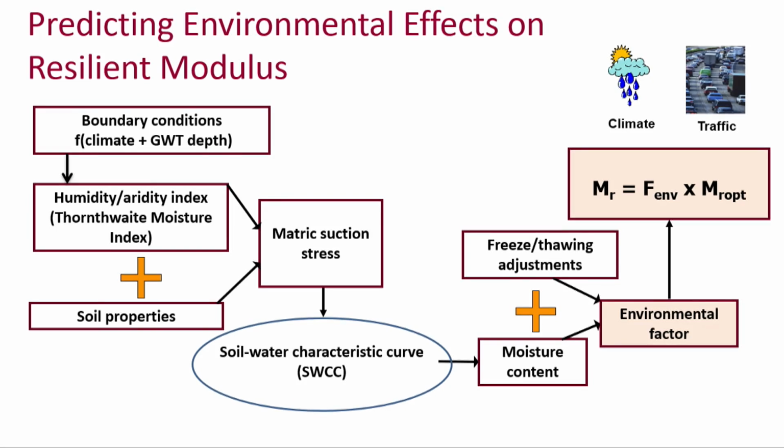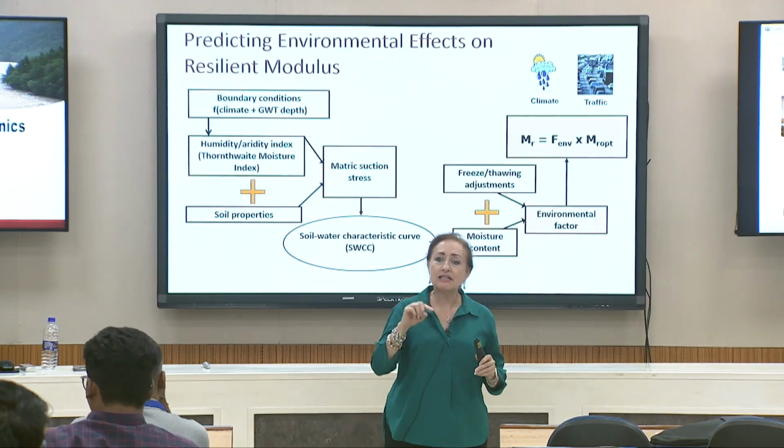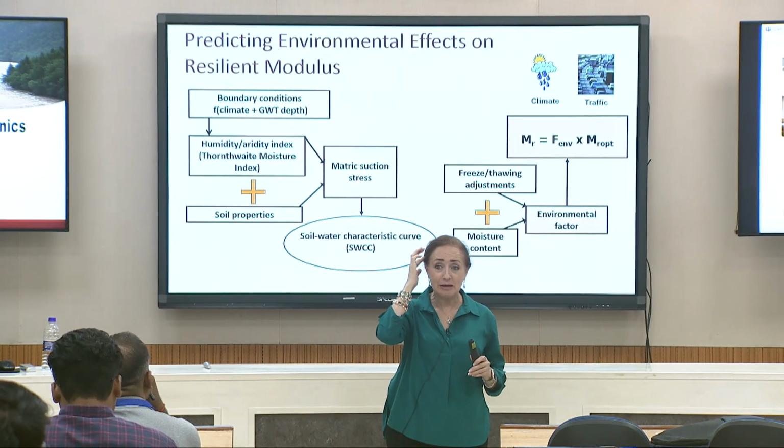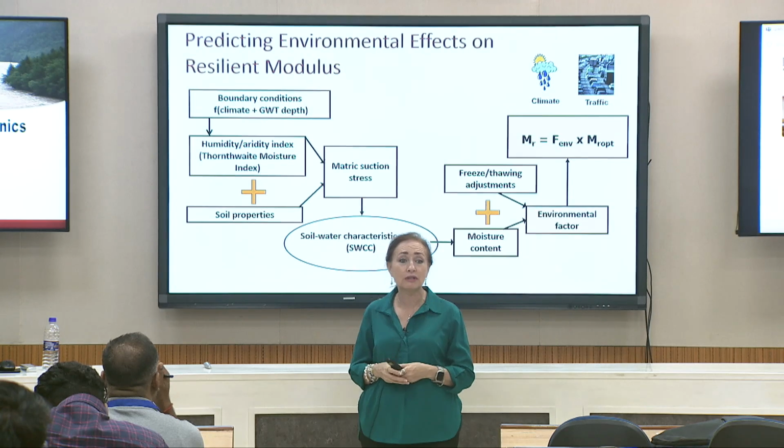And the resilient modulus at optimum, right? When you do the resilient modulus at optimum, what we looked at this morning was that you have a stress sequencing, and you do a dynamic loading that is haversine. That resilient modulus that you get in the lab is actually what represents the response of your material due to the traffic.